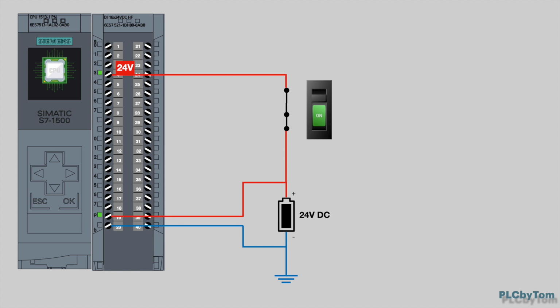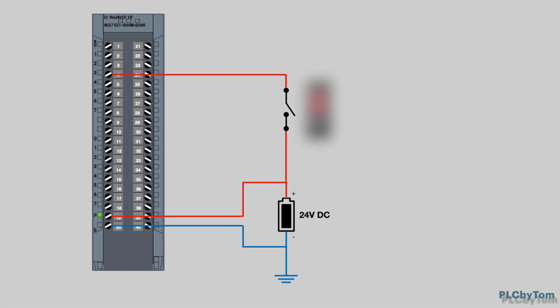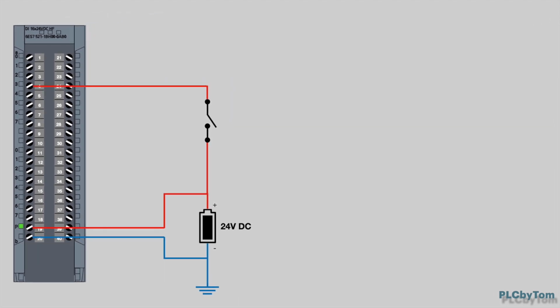Depending on the status of the input module, the digital input module converts received electrical signal to logical signal 1, or true, or logical signal 0, or false, which is a suitable signal for CPU. If we pay attention to the current flow direction, and since it is the direction from the sensor towards the channel, it is a sink type module.